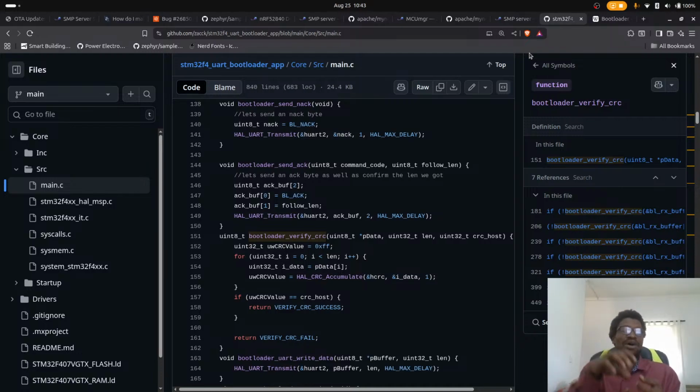If you've done a bootloader, you know there's a point at which you need to disable your interrupts, but then there's a point at which your interrupts also block you, and you can't move from bootloader to the user application. But with Zephyr now, we basically don't need to change.